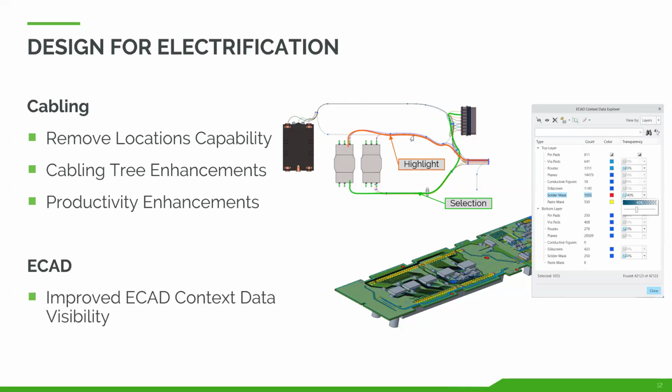For ECAD support, as you bring in your ECAD data inside of Creo, there are now controls to control, let's say, the colors that you're bringing in, the visibility, the transparency of each item that you would have. And in this way, you have better control on what you're deciding to bring in inside of Creo for your ECAD data.